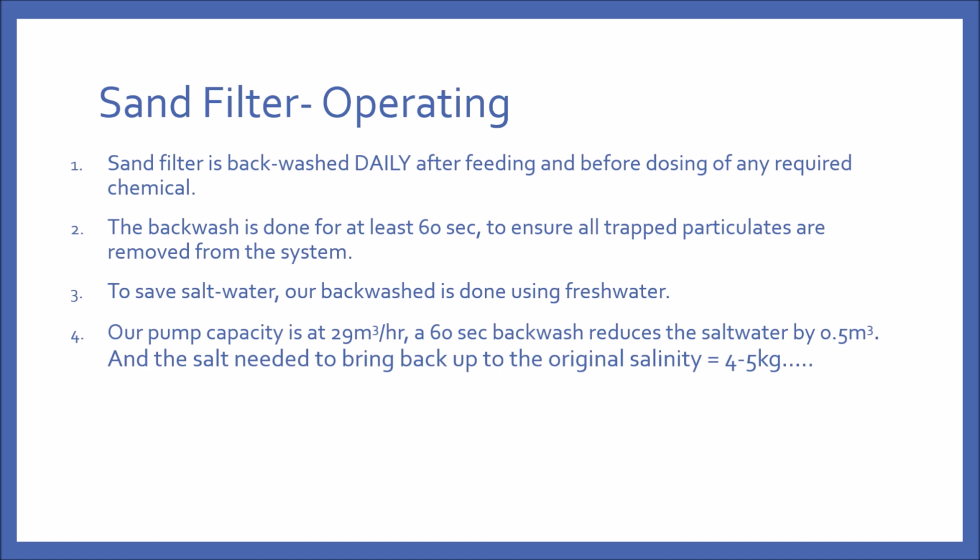We do a backwash of at least 60 seconds to ensure all trapped particulates are removed. However, when backwashing a sand filter system, you usually use system water, which for some of us can be quite costly, especially if you are located far from the coast.